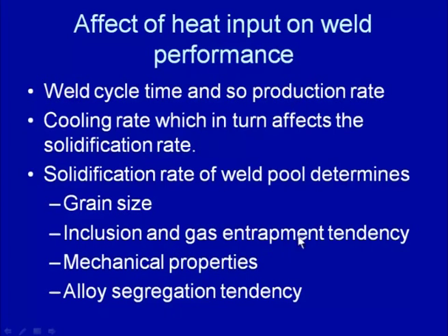And if we see, these two things are just opposite to each other. It is always desirable to have finer grain size to get better mechanical properties, while the increased entrapment tendency for inclusions and gases will adversely affect the mechanical properties.